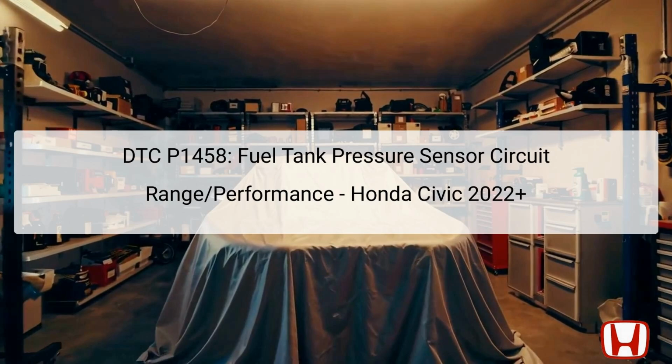The DTC P1458 refers to an issue with the fuel tank pressure, FTP, sensor circuit range or performance in the Honda Civic 2022 and newer models. This error indicates that the pressure inside the fuel tank is outside of the specified range after engine shutdown. The Powertrain Control Module, PCM, monitors this pressure, and if it detects abnormal values, it will trigger this error code.